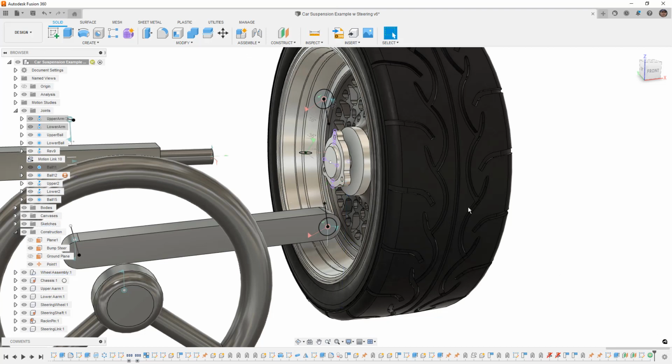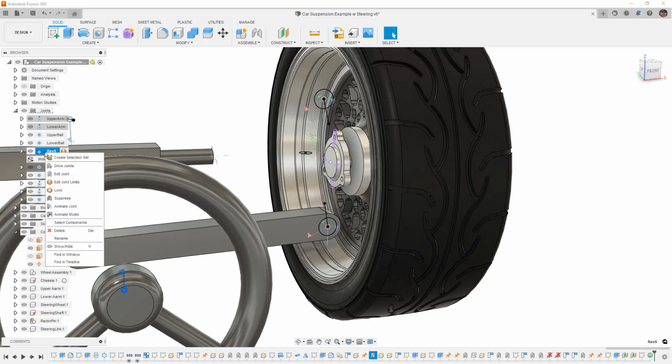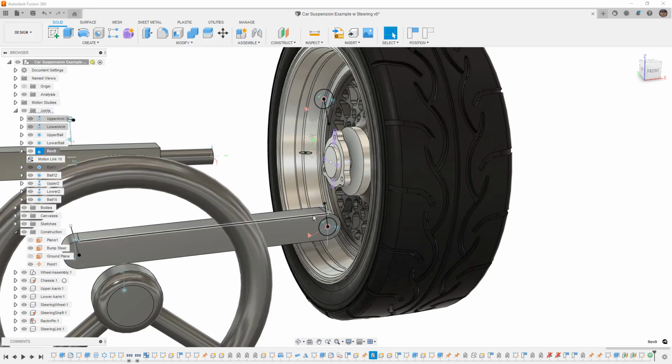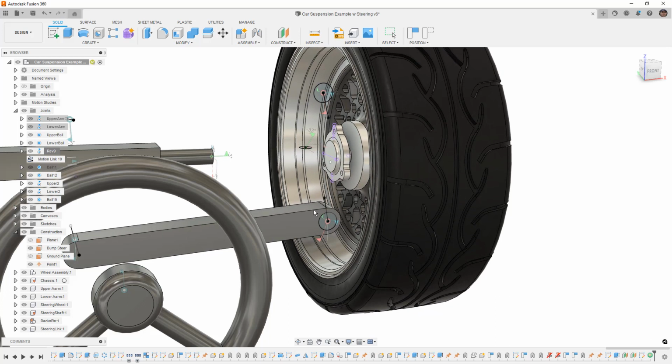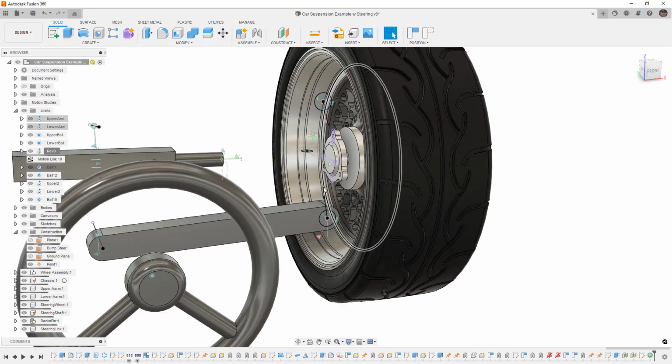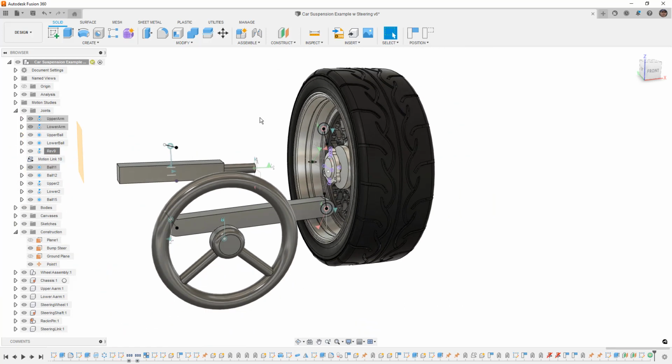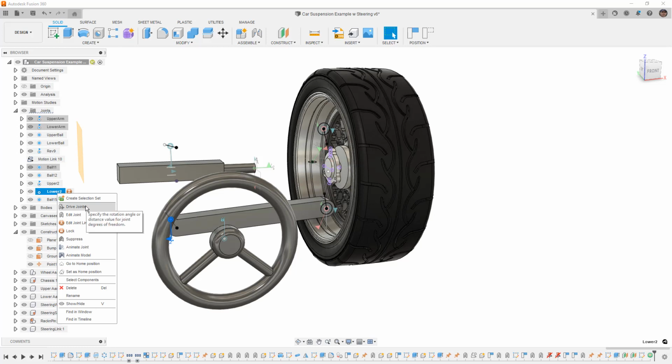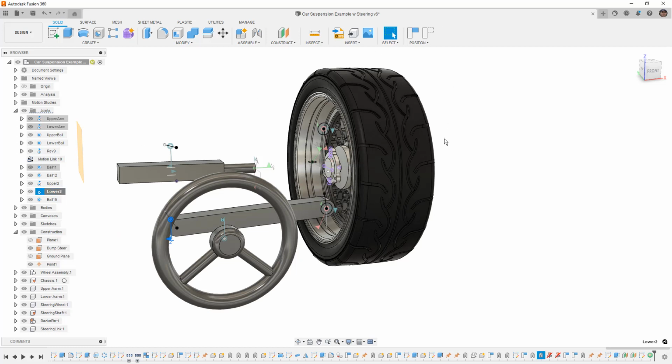So now that we have that base number, again, we need to make sure that this joint is locked. Every time we revert the position, it's going to unlock, and then we can move it up. Now, the best way for you to really do this is to probably have a shock or some sort of joint that you can drive the height or the angle. Now, we could drive the angle of this lower by doing things like animating the joint or driving the joint. But in this case, I'm just going to manually move it so you get an understanding of what we're doing.